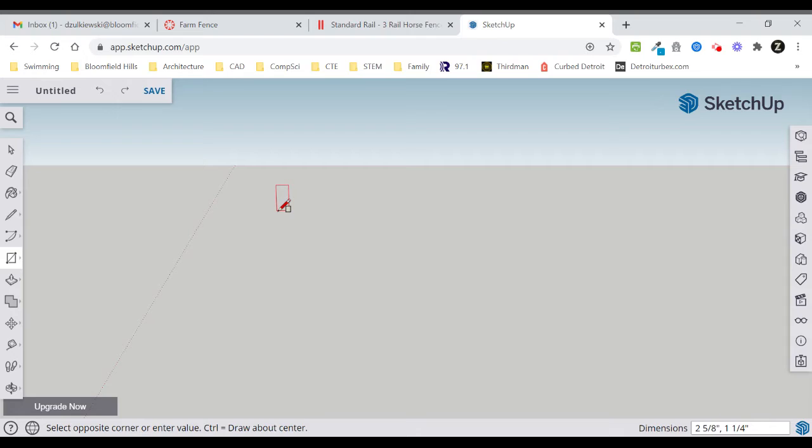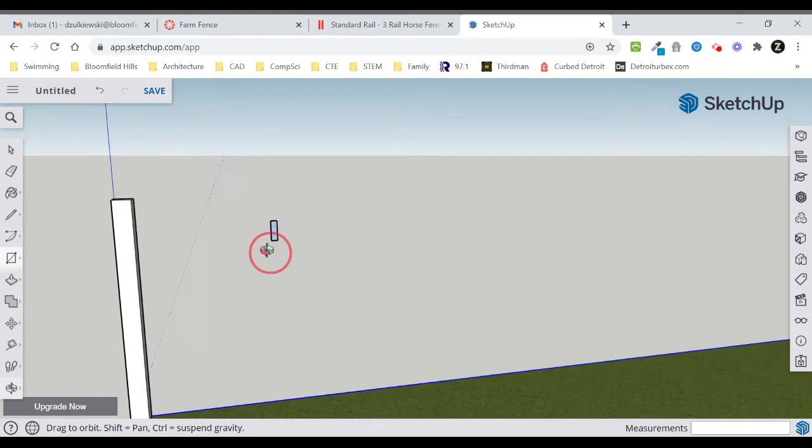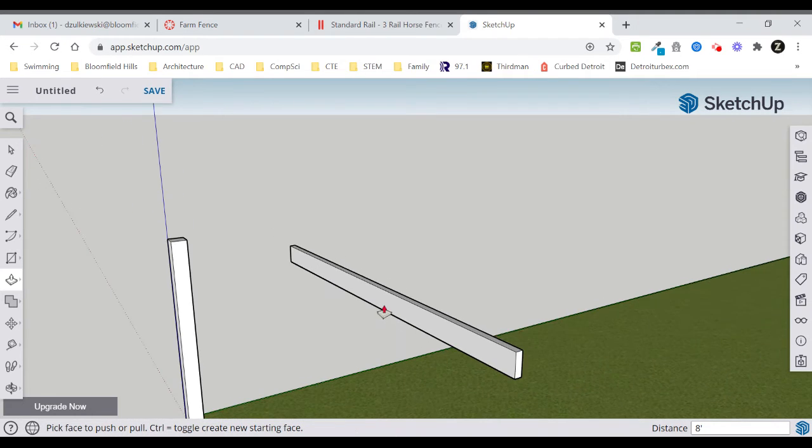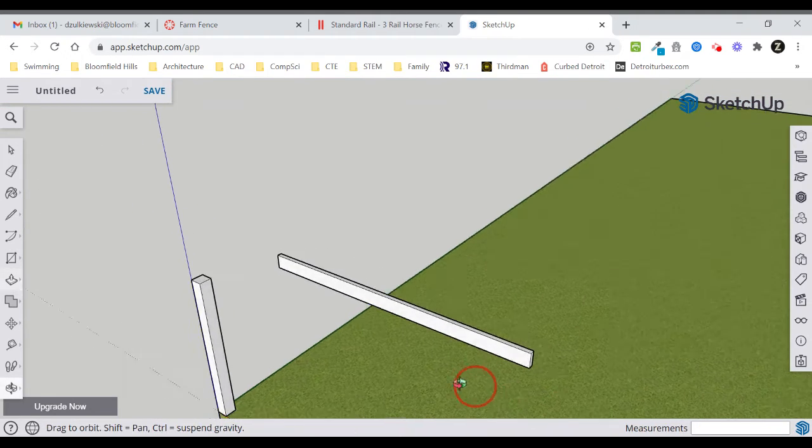All right, just got to make sure we have the right rectangle. So I'll do 5 inches, comma 1.5 inches. There we go. It looks a little better. All right. And then I just use the extrude tool. And I'm going to pull that 8 feet. Again, check the dimension in the bottom right-hand corner. And I'm going to hit enter. And I have this railing.